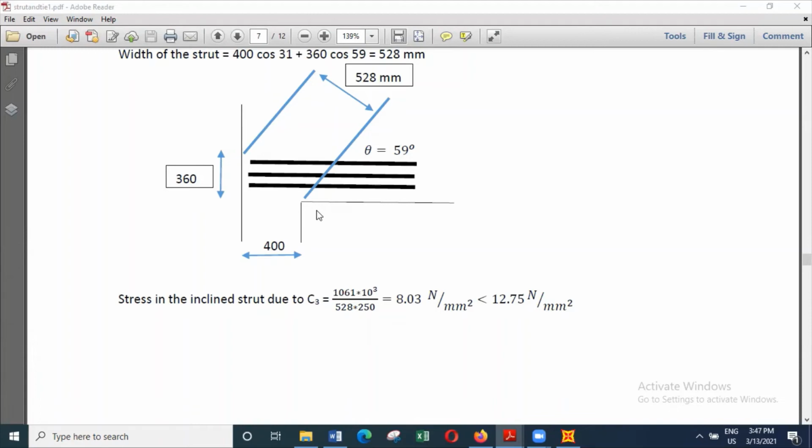So this is a common situation that can arise in shear walls, where the shear wall is supported by two piles and a ground beam. So generally you can have two piles and a ground beam and support the deep beam directly on the piles. You can have something like a capping beam representing the pile cap, and then on top of that you can support the wall.